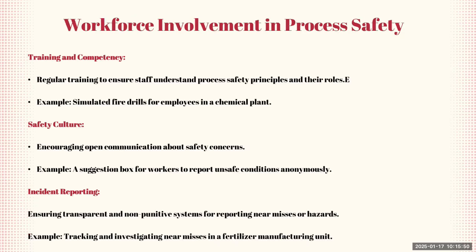Then we have also the workforce involvement in process safety. So we need to ensure training and competency. So regular training to ensure that staff understand the process safety principles and their roles. So not everyone on site will understand how a process works, but it is important to tell everyone, okay, perhaps when the operation is happening, do not go close to this equipment, for example. So it's important to also simulate different drills, like fire drills. Let's say there's an emergency scenario. Where do we proceed? Where do we move? This is important.